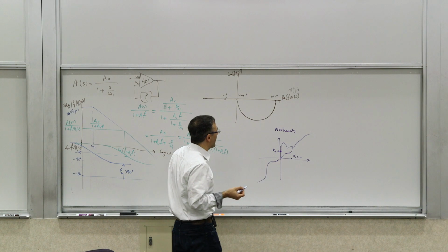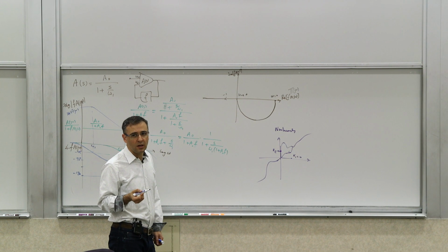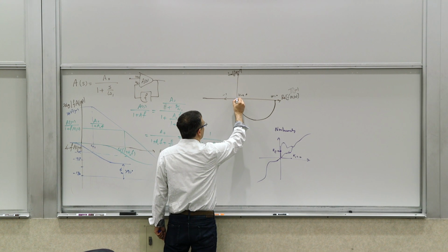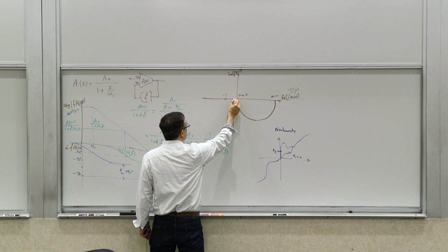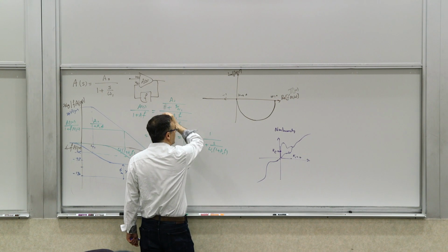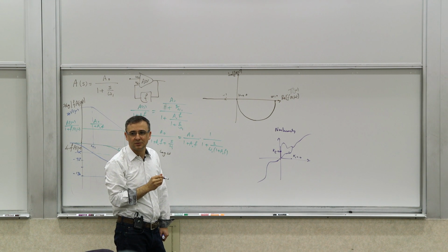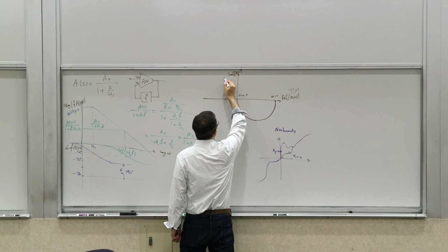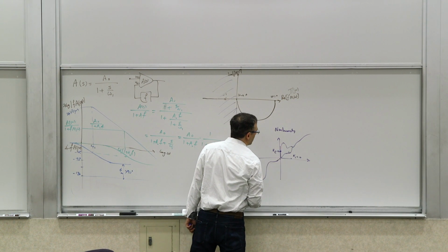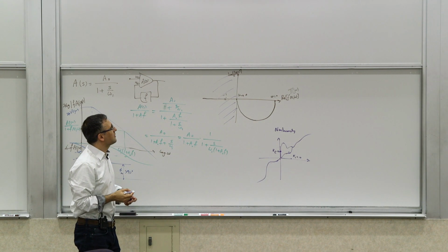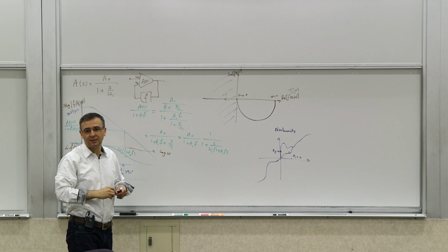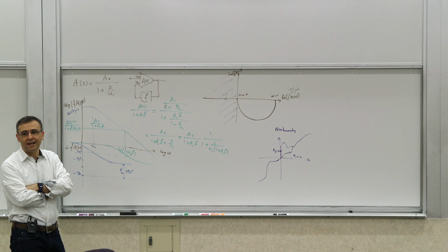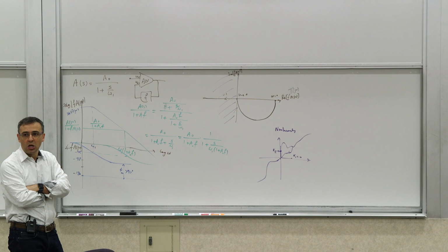And what kind of area does it correspond to? If you think about it, it's a circle. One end of it is at 1 over 0 here, and the other one is at 1 over infinity. Right? So for this kind of nonlinearity, as long as it's confined to first and third quadrant, as long as you avoid the left half plane, or left side of the plot, the negative real part for the loop gain, you are stable.